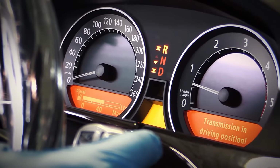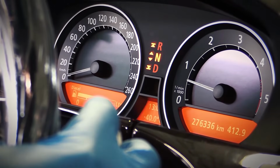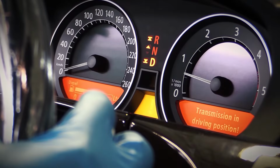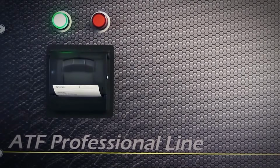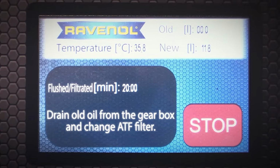During the flushing process, the newly added ATF fluid will dissolve impurities in the transmission, and the device filter system will continuously filter it out. As a result, it is possible to ensure that impurities in the transmission are removed. The completion of the flushing process is indicated by the green indicator light on the device. Once the flushing process has been completed, a static oil change must be carried out.